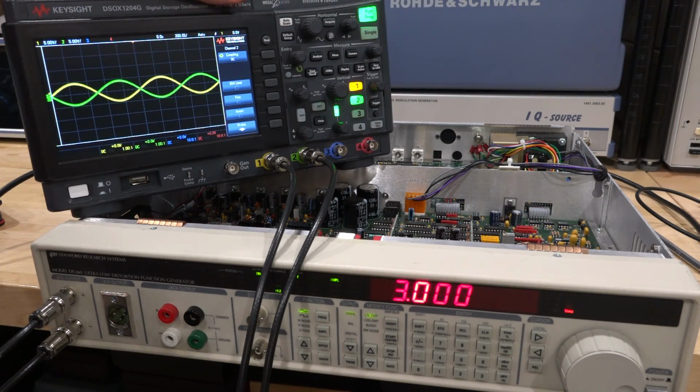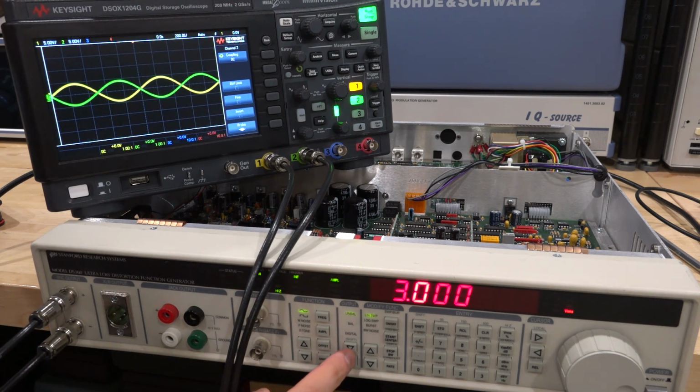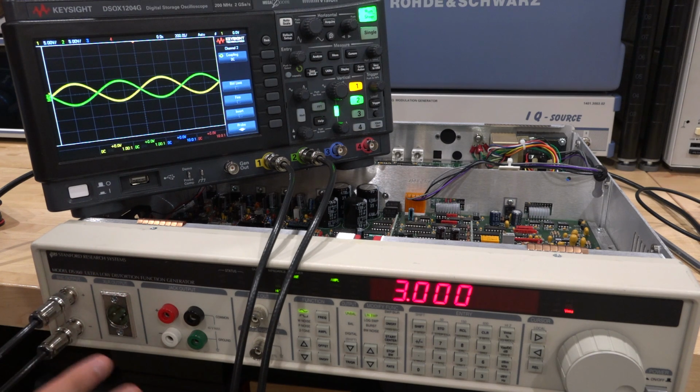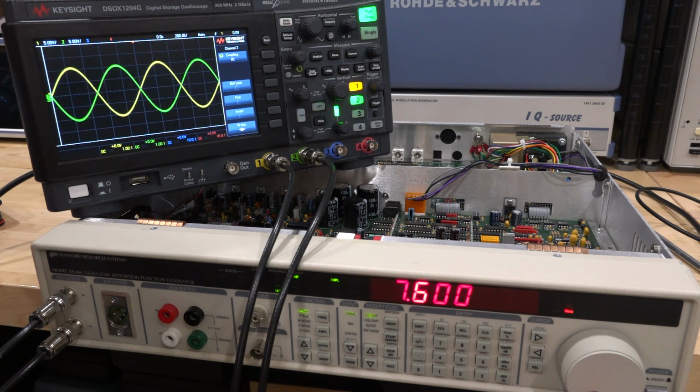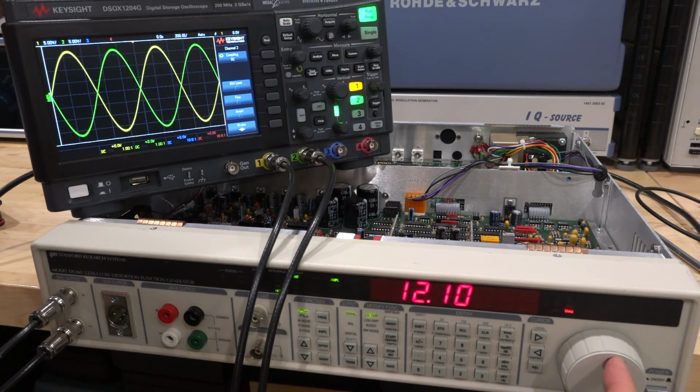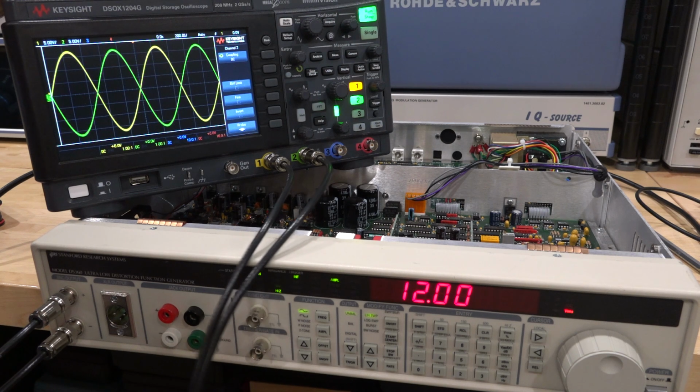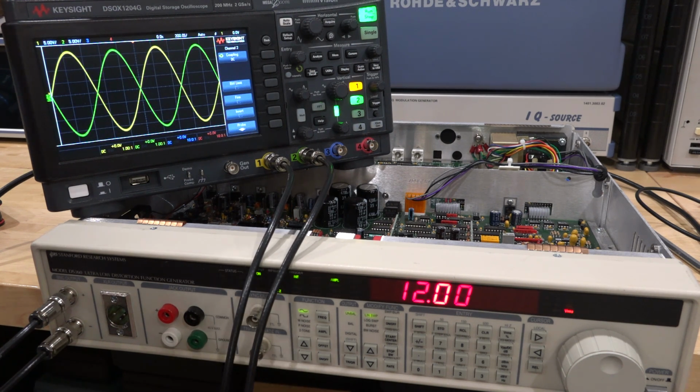Indeed, we do get an output now, both on the plus and minus outputs. And if I change it between balanced and unbalanced, the output doesn't change, but the reference ground between the two of them does change. And that does have some implications on the linearity of this thing. But I can change the amplitude. Look at that. I can just keep going. And here it is 12 volt RMS, and it is a very large signal there. Right now we're driving into high impedance, but we can change the output, actually as well the output termination. We can play around with that.